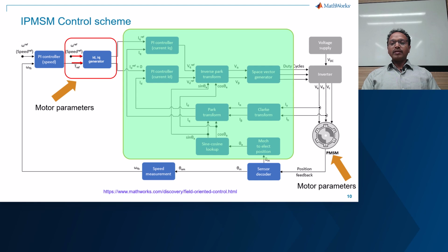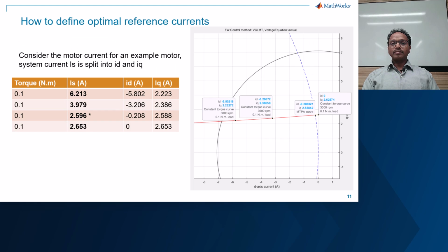So how do we define the optimal currents now? What is optimal about this? This could be the current that results in the highest torque or highest efficiency or any system level behavior for the lowest amount of current. For example, a motor may generate the same torque for different input currents, but there exists the lowest amount of current that can still produce a required torque.